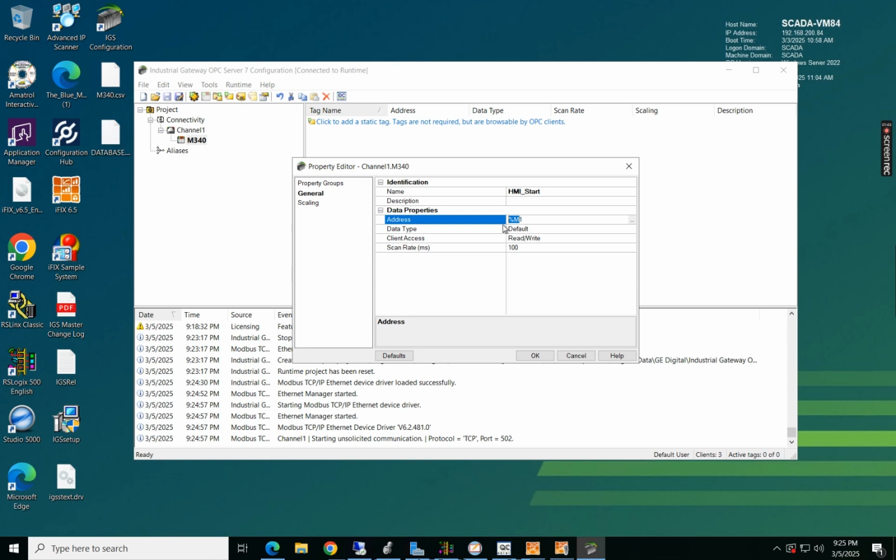And to do that, you'll want to take this %M out and then you add 1 to this last digit, so that'll make it 2, and then in front of that, put 5 zeros. And that will convert it to the correct address.